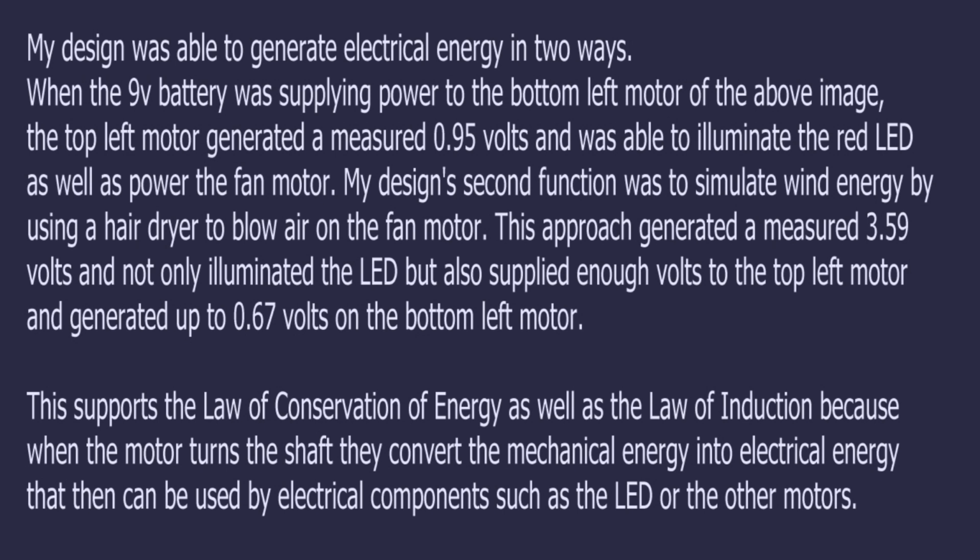My design's second function was to simulate wind energy by using a hairdryer to blow air onto the fan motor. This approach measured 3.59 volts and not only illuminated the LED, but also supplied enough volts to the top left motor and generated up to 0.67 volts on the bottom left motor. This supports the law of conservation of energy, as well as the law of induction, because when the motor turns the shaft, they convert the mechanical energy into electrical energy that then can be used by electrical components such as the LED or the other motors.